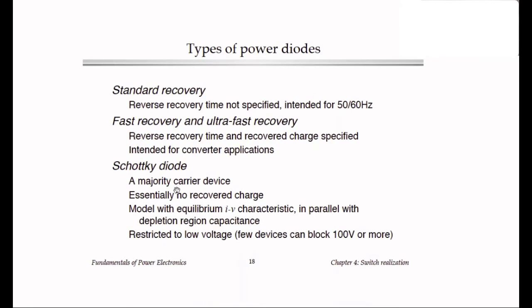So there are commercial devices that have found some good industry acceptance. The major problem today is that they have a very high cost. A silicon carbide 600 volt diode might cost 5 or 10 times as much as a normal silicon diode, but they definitely have some measurable reduction in switching loss.